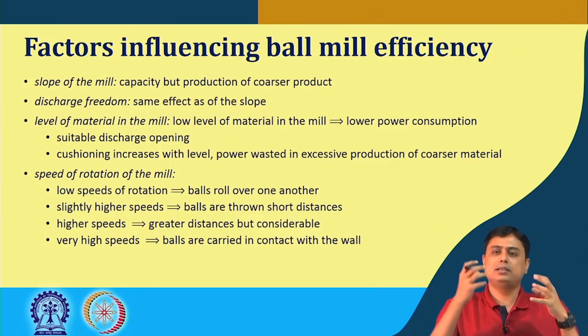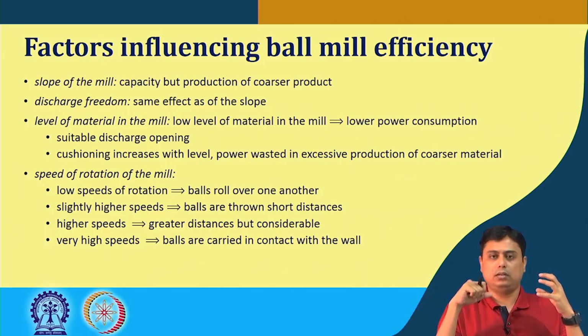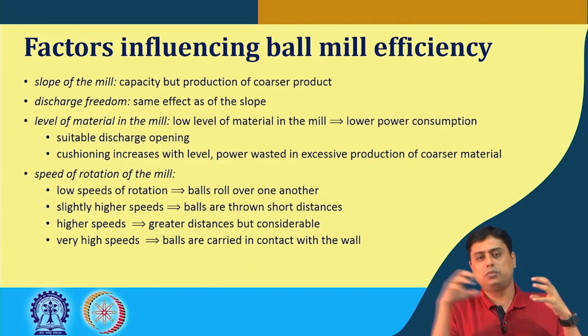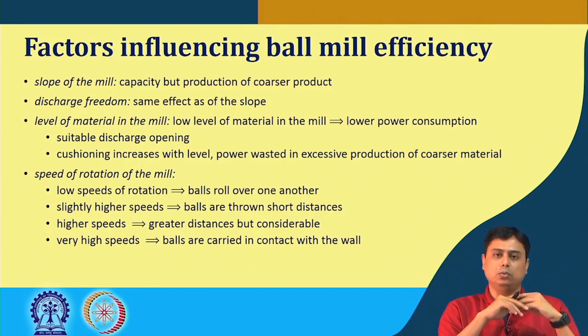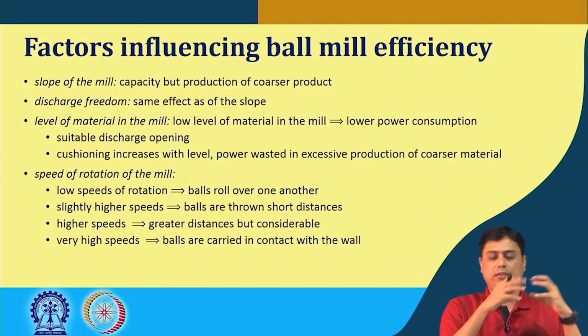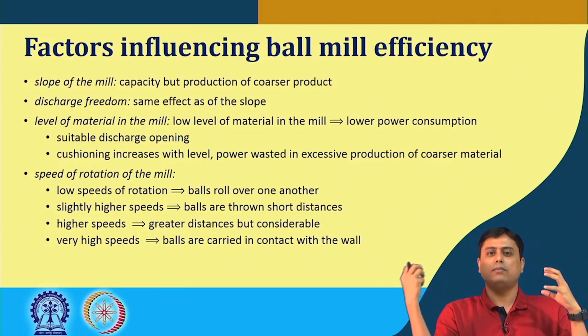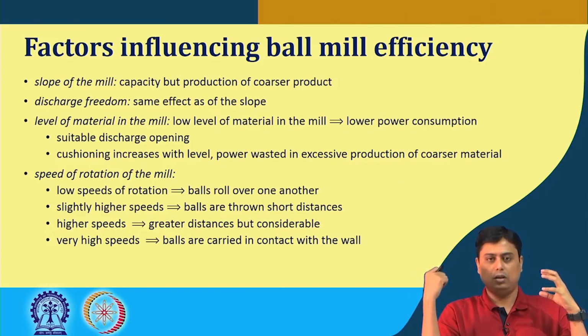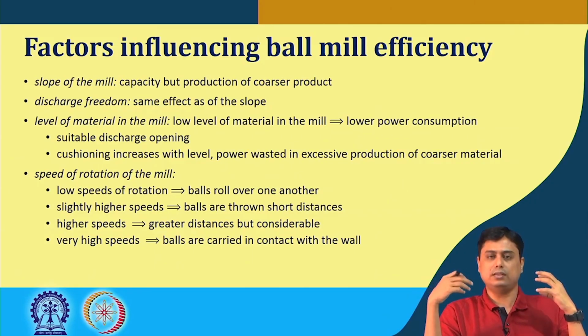Discharge freedom, that means how easily you can take out the product. If that is smooth enough, it has the same effect as that of the slope. If the discharge comes out quickly, that means the residence time is lower, so there is less significant size reduction.